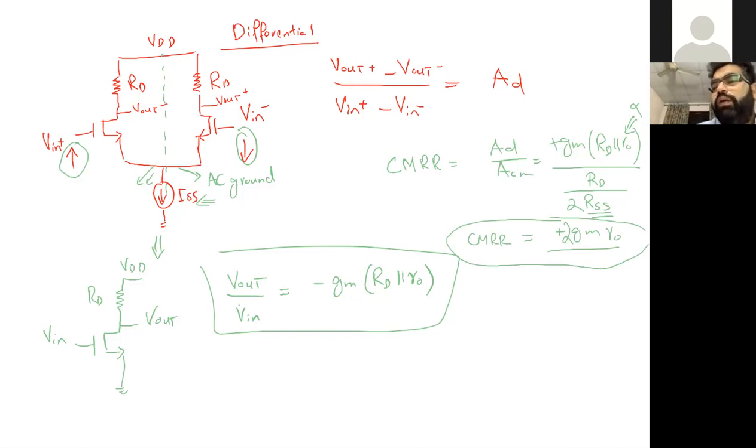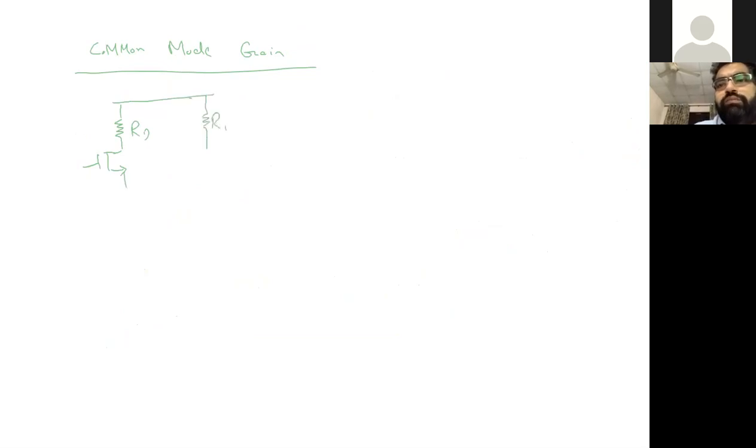But one important thing also is to do the common mode configuration for the common mode gain. We can also do common mode gain using the same differential approach which we have seen. So how can we do that? We just mentioned this stuff that okay, we have here something RD, right here RD. If we want to see another way, which we are all familiar with, using a small signal model, and here we have some ISS.